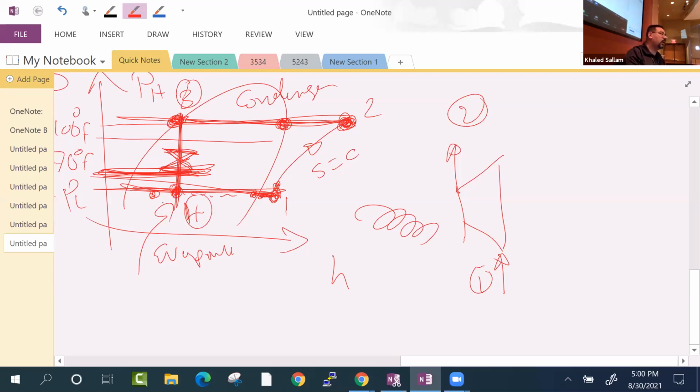So as the pressure drops like a rock, the temperature also drops like a rock. Okay, and you are ready to go into the evaporator. So what is genius about this, at least that's what I thought was genius when I was an undergrad, is that you are still doing the natural way of moving heat. You're always moving from hot to cold, but by this cycle you still manage to take heat from low temperature and dump it at the high temperature.